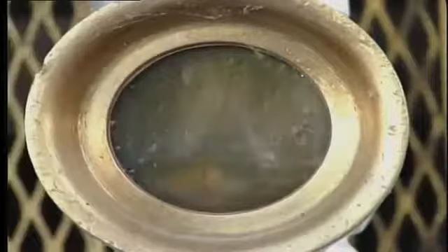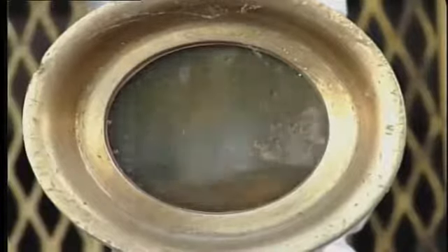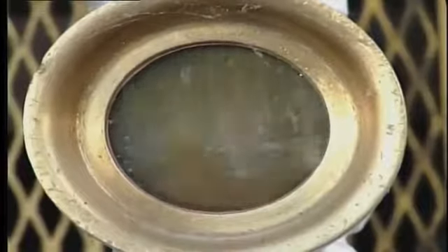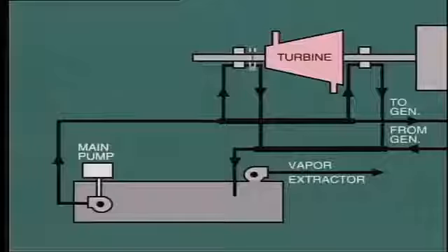Well, so much for sealing systems. Another very important support system that is essential for turbine operation is that of lube oil and hydraulic oil supply. Let's look at the lubricating oil system first. A continuous flow of lube oil must be circulated through all of the turbine and generator bearings. Typically, the arrangement would look like this for a single-cylinder machine.